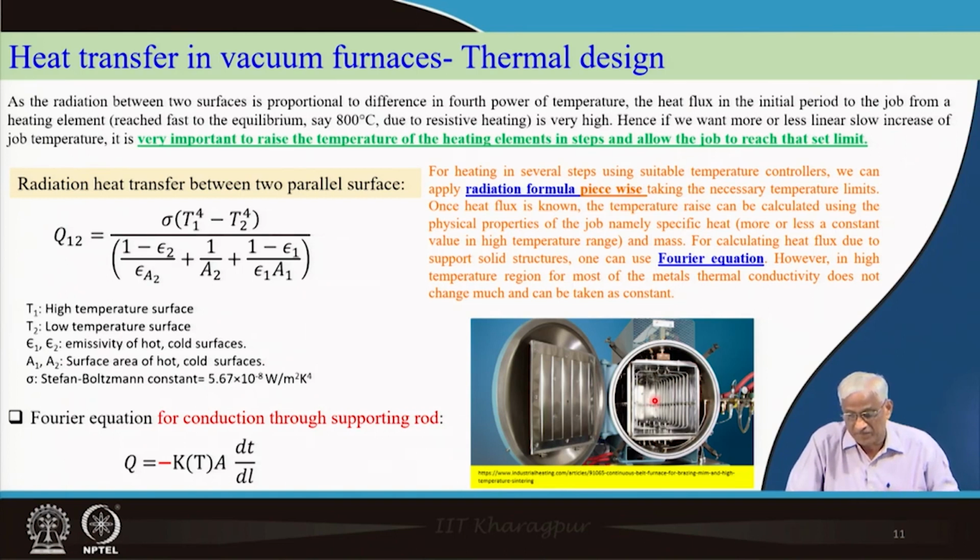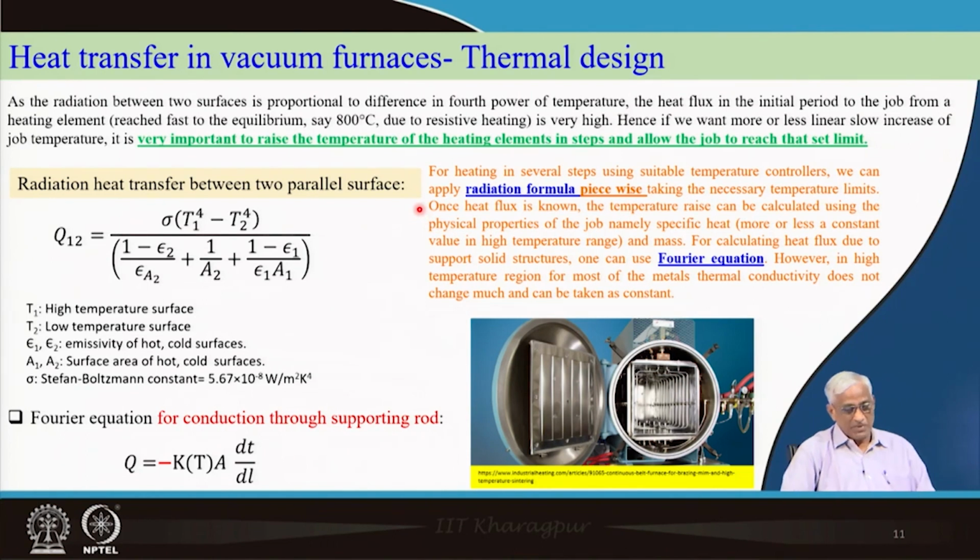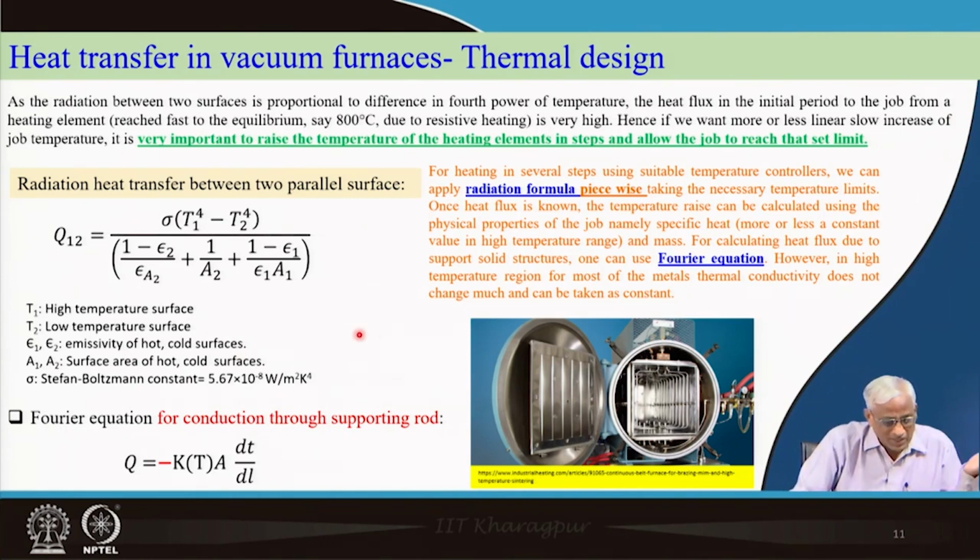Job will be here finally, and there is heat loss to the surroundings from radiation to the chamber, and conduction through the unavoidable support structures. If you can do all that, the heat flux is properly utilized to reach the temperature. So, these heat transfer calculations I leave to you. You can easily understand the various temperatures, and you have to do it iteratively.